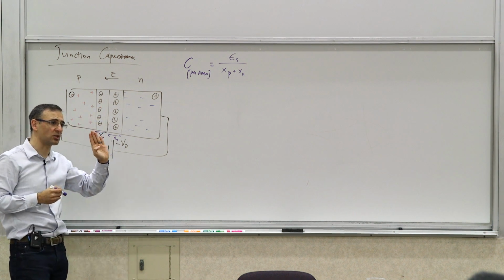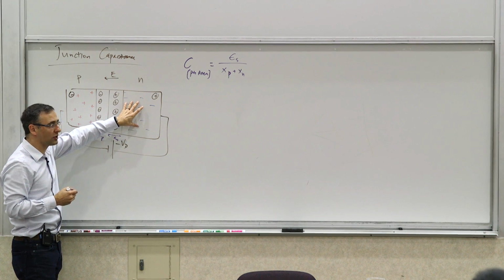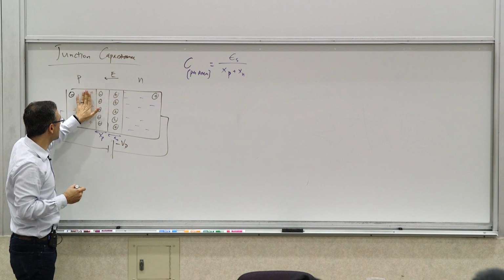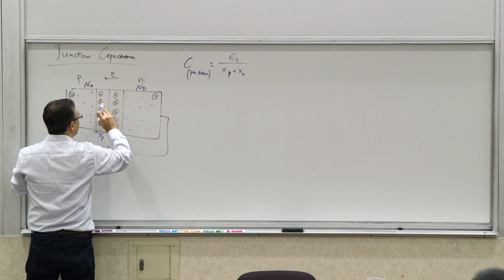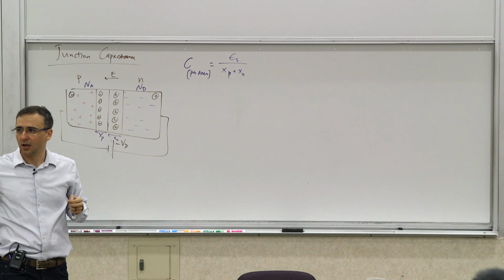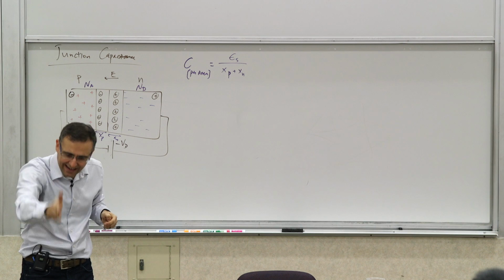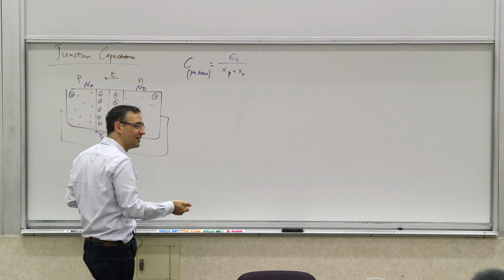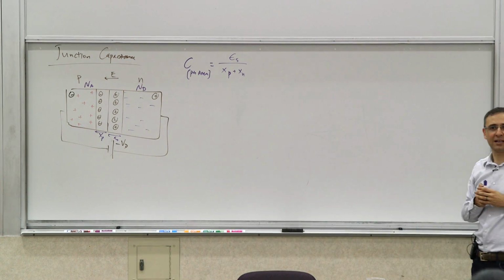So now we are making an assumption so far. The assumption we are making right now is that the doping concentration is uniform across this entire region, and it abruptly transitions to the doping concentration here. So on this side you have Na, and on this side you have Nd, and that's constant. This is basically called an abrupt junction. A junction where the doping concentration is constant up to a point, and it instantaneously changes to a different level. Now, making such a thing is hard. You can make good approximations of it, but you can never make something exactly like that.